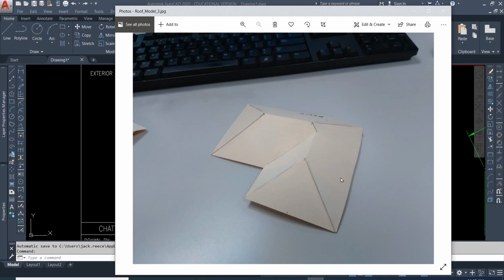Okay. Now this end of the roof is the same as before. You've got to do the calculations over again because the width of the roof is different. And then you can take this piece that you drew and lay it on top of this piece and trace it so that you get that corner right there. And then these two pieces of the roof will be identical. And then you calculate again for the hip that goes on that end.